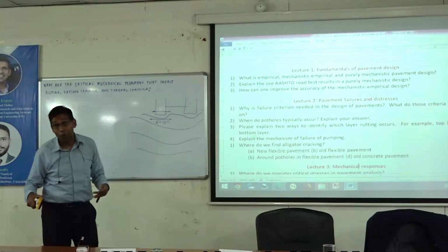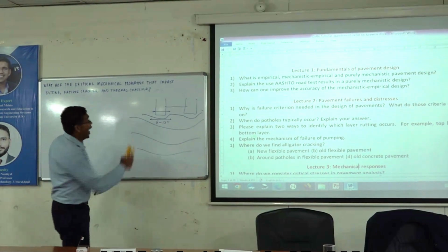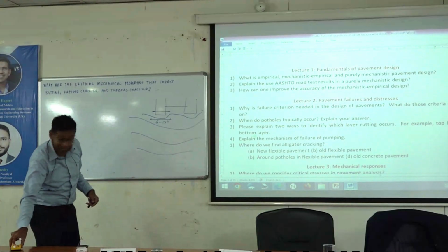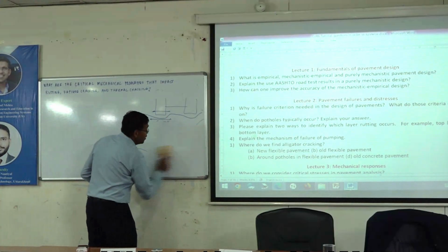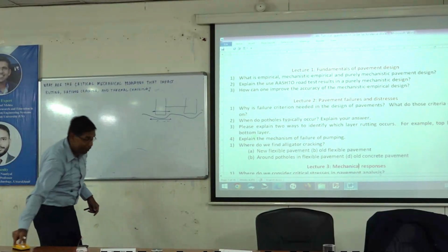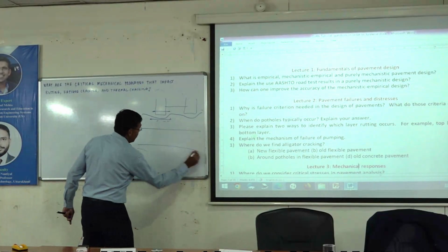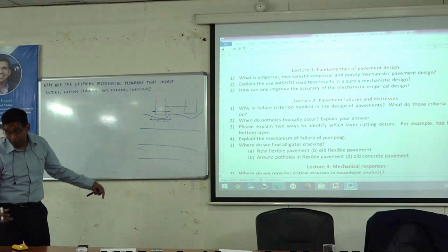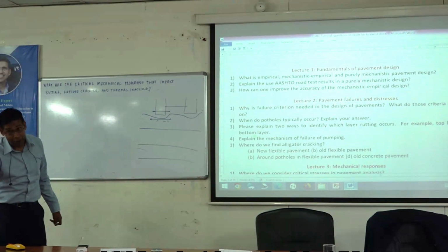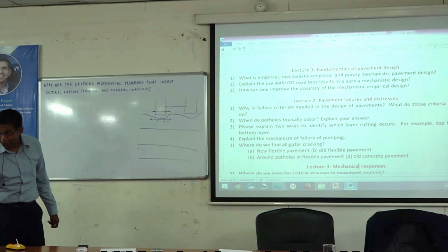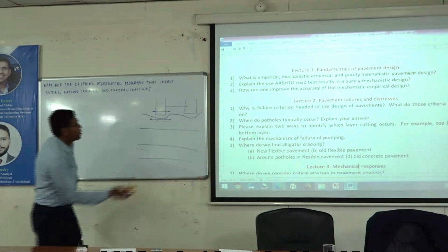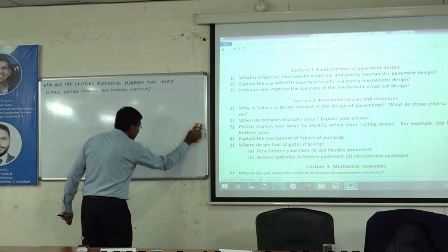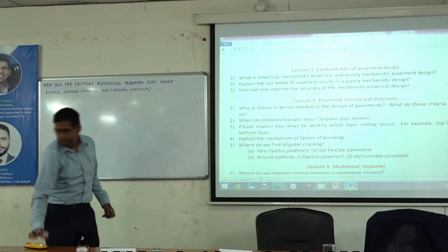Yes, you have to cut the whole section of the roadway. You have to actually slice the entire roadway, and if you slice the entire roadway, you will see something like this, and then now you know. That's the most thorough way, which no DOT or PWD will like to do. Nobody likes to make holes in the roadway. So that's the most exact way: you have to make a cut in the entire roadway and see what's going on.